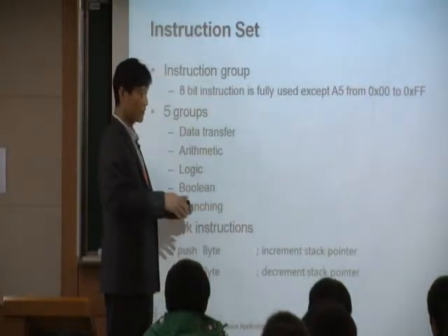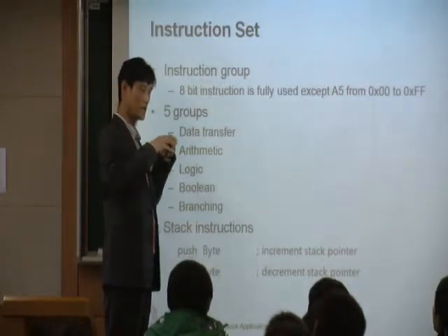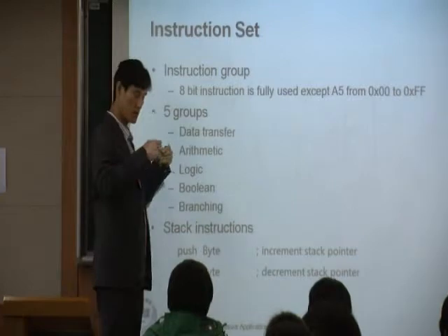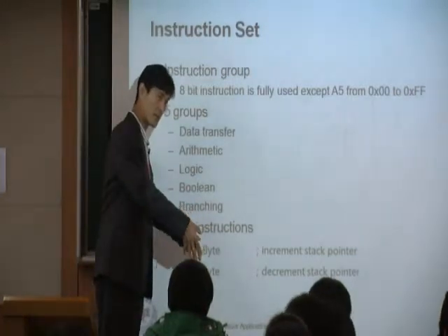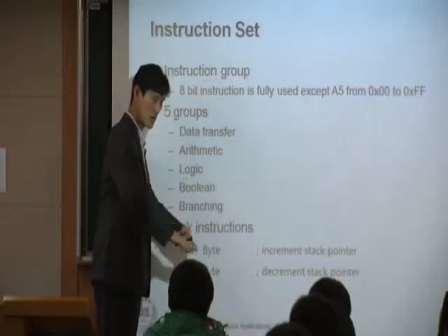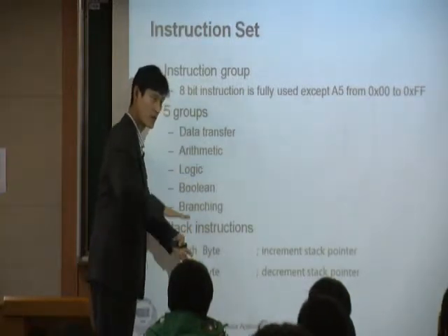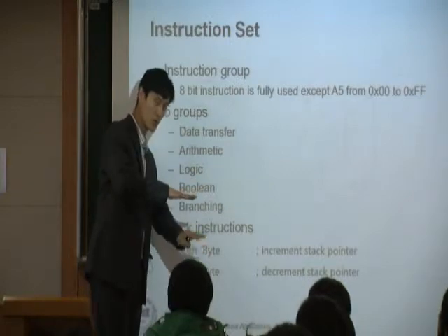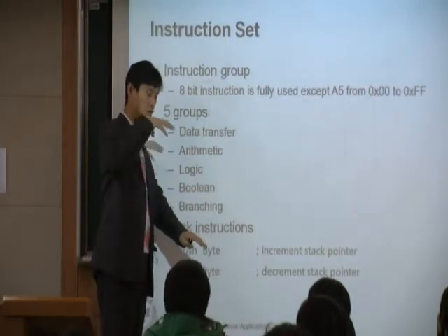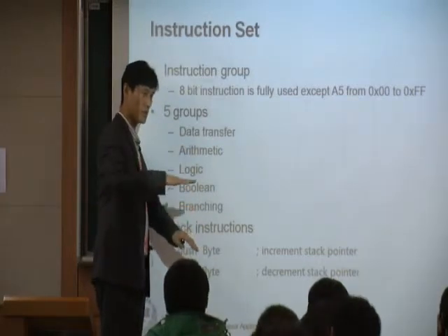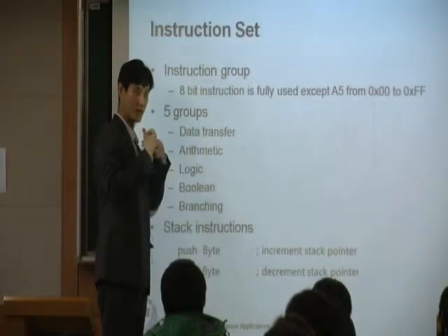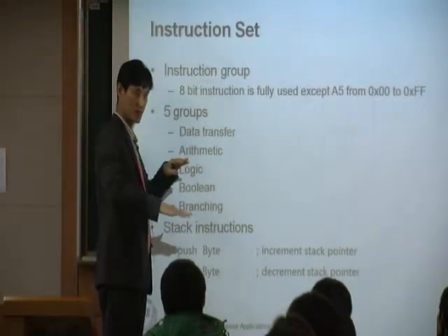Now if you push one thing into the stack, for example I push one book into my box, then your stack pointer is increased because the floor is now higher. So every time you push, the stack pointer will be incremented. And every time you pop something out, the stack pointer will be decreased.